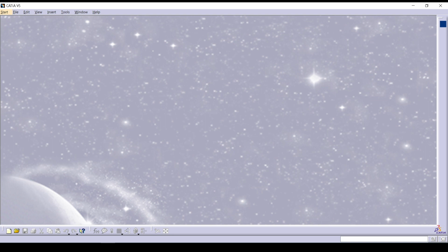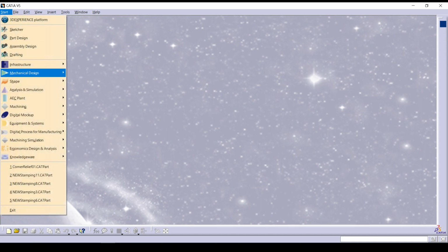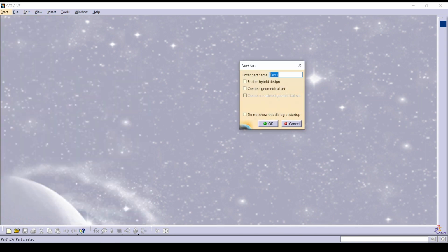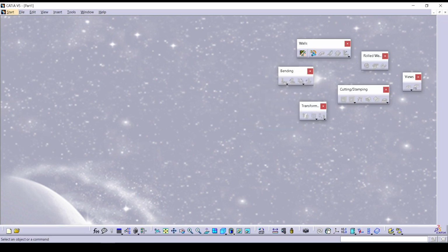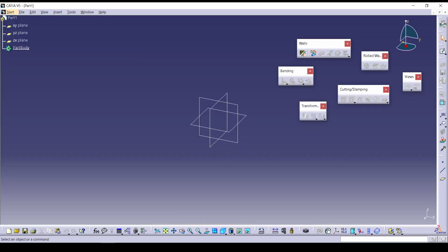It allows you to fold and unfold the representation of the part, and one more advantage of sheet metal is we can work with the sheet metal part in other applications like part assembly and drawing generation. And in the sheet metal part there are many standard features like stiffener, stamp, shape and sweep features which reduce the design error.